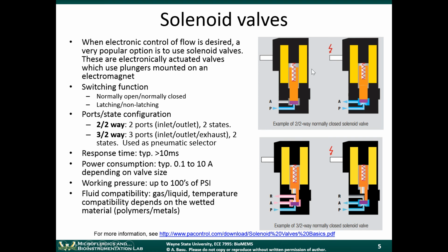Another important parameter when we're talking about valves is what types of fluid can you run through there. A lot of valves are only designed to allow air to go through them. So they're designed for gases. With liquids, you have to be a little bit more careful. And if you're working with corrosive materials like acids, then you have to be even more careful. So consider the material of the pump, what material is being wetted in the pump. Typically, a manufacturer will specify what materials are allowed to be wetted inside the pump.